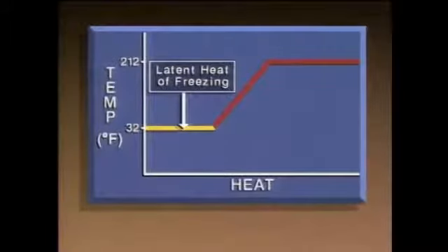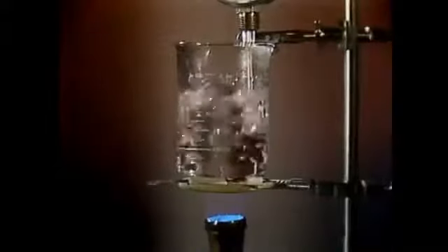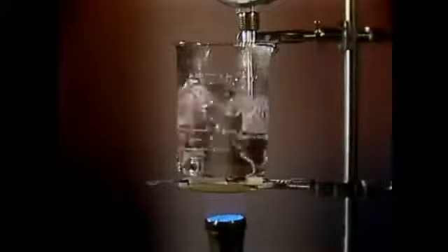The latent heat of freezing is the amount of heat that has to be removed from a substance to freeze it without producing a change in temperature or pressure. When a liquid boils, a phase change occurs. A substance changes from a liquid state of matter to a vapor state. The boiling point of a liquid is affected by temperature and pressure. To show how temperature and pressure affect boiling points, we'll use water as an example. But the same basic principles apply for all liquids.